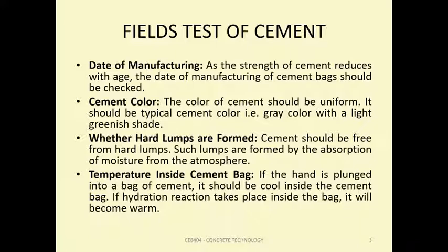The next one is to check whether hard lumps are formed inside the cement. The cement should be free from hard lumps, because lumps are formed by the absorption of moisture from the atmosphere. Then, checking the temperature inside the cement bag. If we insert a hand into the bag of cement, it should be cool, because if hydration takes place inside the bag, it will be warm.